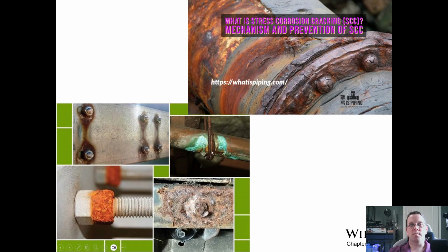So had this been insulated with a rubber layer or some other sacrificial insulator, something that prevents direct ion exchange between these, there wouldn't have been this level of corrosion. So similarly, maybe you have a zinc type steel nut on this side and you have a mild steel nut on this side. One gets corroded while the other doesn't because of the dissimilar nature of the two materials. That can happen very commonly. So you see sort of the white oxide layer around this, but you see the very heavy corrosion around what was probably a mild steel part.